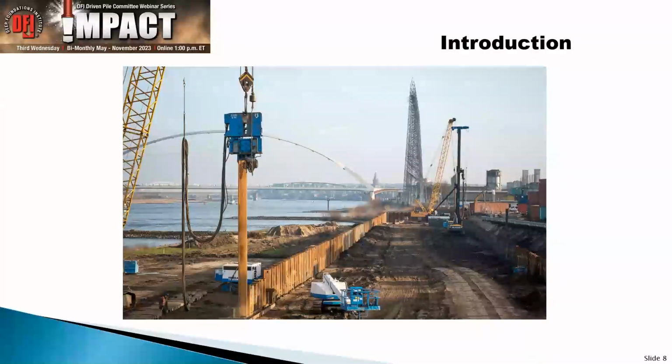And why can we drive a steel sheet pile into the ground with a vibratory hammer and nobody's asking any questions about it? And why would we have some reluctance to do it with an open pipe pile, for instance, where people are saying, well, maybe we still need to use an impact hammer, especially for the final part of the driving process. True enough, when you have a sheet pile, you generally are not that concerned about the bearing capacity of that pile. But hopefully, as I pointed out earlier, I can show you that we can do the same thing when you drive a load-bearing pile with a vibratory hammer.